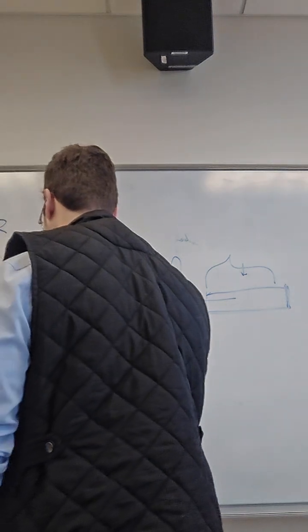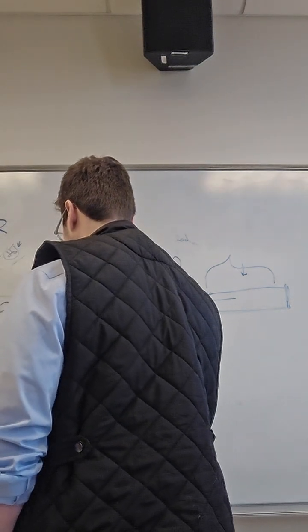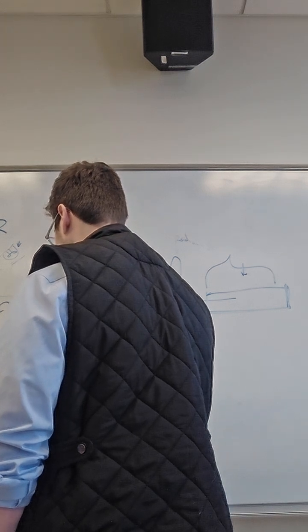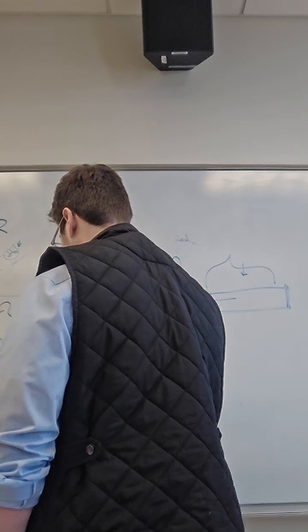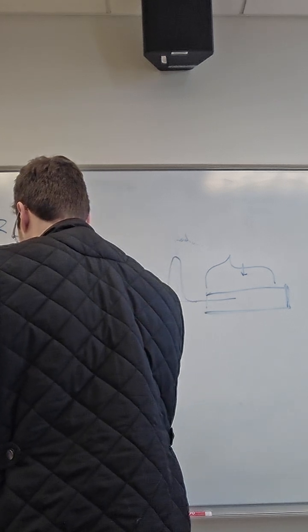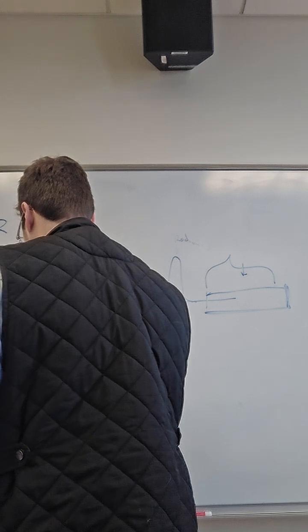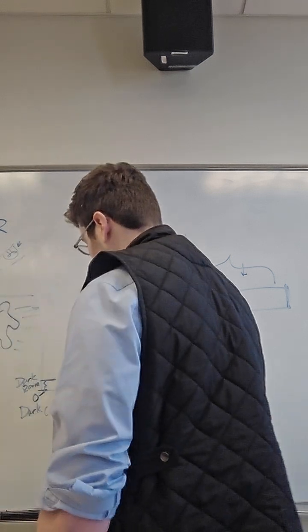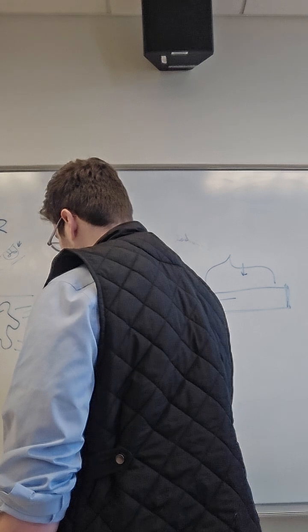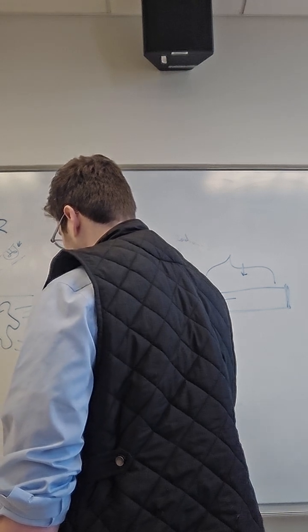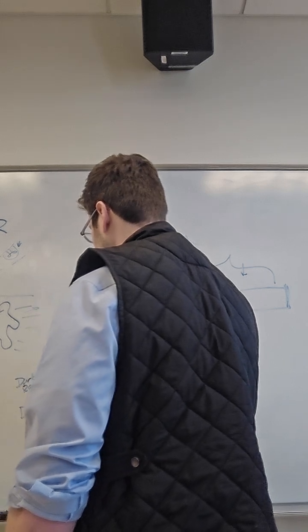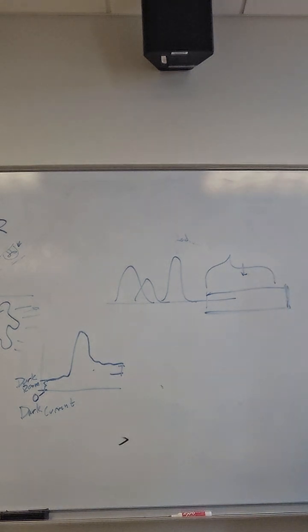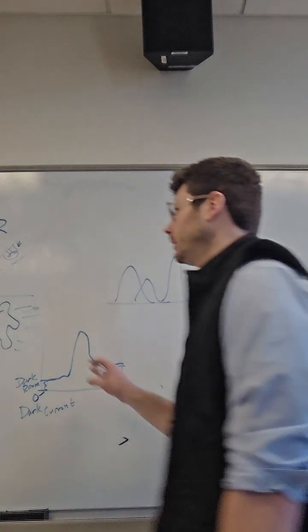We get some probably voltage from that, right? The difference between absolute zero, this is called the dark current, and probably like an actually dark room is some amount, right? And then when a person walks in, we will see that jump, right? It's probably really high as they walk through the door, and then raised probably a little bit ever after as they continue to inhabit the room. And that's something that we could see, that's something that we could detect.